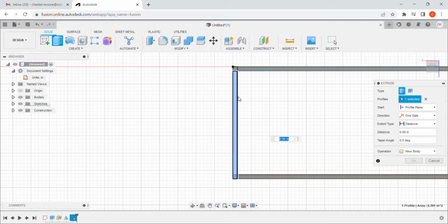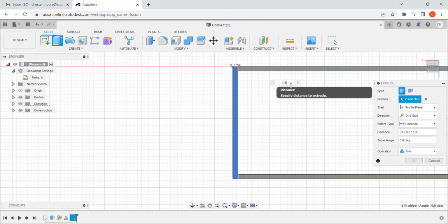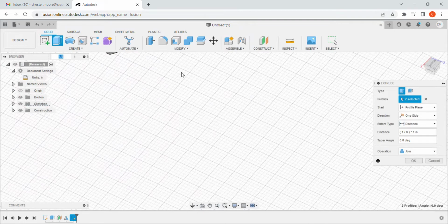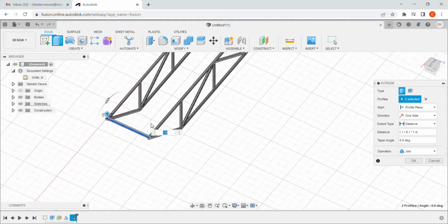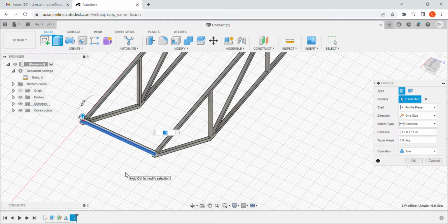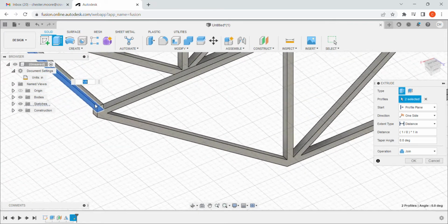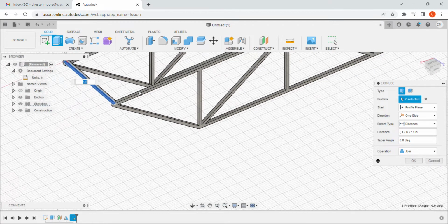Let's select the body. Now, if you notice, it only selected some of it. It left this little tiny rectangle out. I can use my shift key and highlight that and make it part of it. And now I just want to extrude it 1/8 of an inch. I want to pull it to the side using my shift key and my center wheel to kind of make sure that it extruded in the right direction, and it went a little crazy because I'm using my mouse pad here. I don't actually have my keyboard here, or my mouse here. So okay, that looks like that worked.